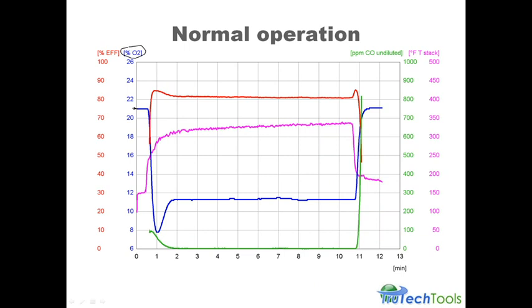And that excess fuel resulted in consuming an excess amount of oxygen for just a split second. And then that O2 level came up and stabilized. Because we had excess fuel, if you look down at the green line on the bottom, we also had about 100 ppm of CO at light off, right? Excess fuel, lean on the air, and we get a little bit of CO. And that air is really not lean. 8% is a pretty good amount of air going in there.